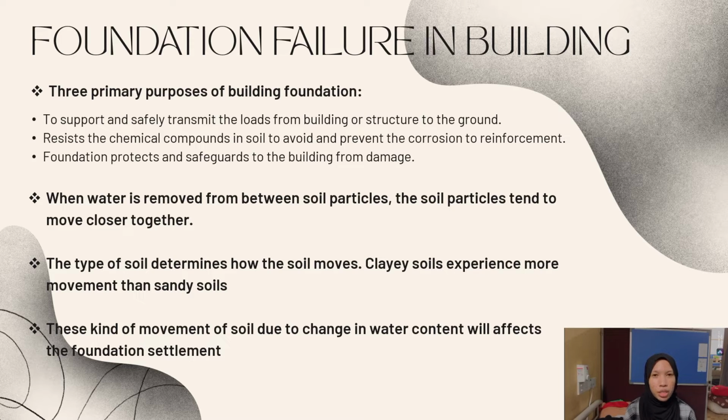And then for the application of this foundation failure in the building, when water is removed from between soil particles, the soil particles tend to move closer together, and the type of soil determines how the soil moves. Clay soil experiences more movement than sandy soil. The last one, this kind of movement of soil due to change in water content will affect the foundation settlement.